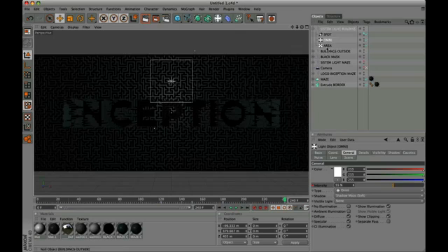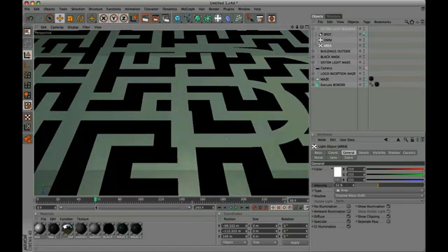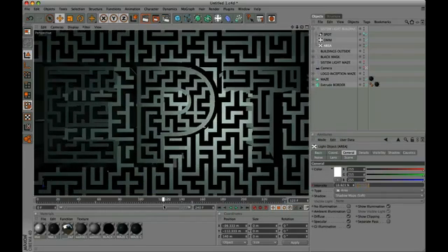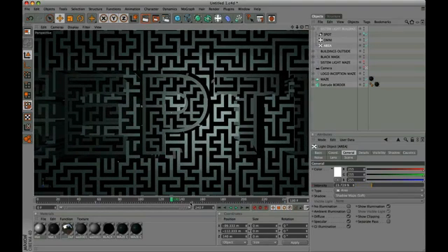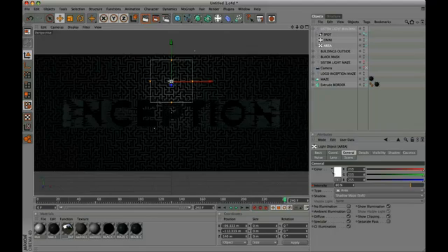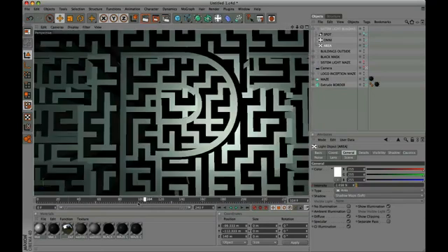Finally, click on Area, and insert a keyframe at frame 56, with intensity 0. Move the keyframe from 150 to 130, and modify intensity from 33 to 10. This system of lights for the buildings was prepared for the final rendering.